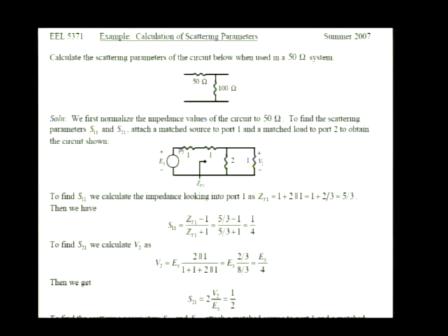Part of ES falls across these 2 resistors, and the remainder, V2, falls across the parallel combination of the 2 ohm and 1 ohm resistor. That's the part I want. How much voltage is there across that parallel combination? So, use the voltage divider rule. The voltage divider rule says the voltage in question is equal to the total voltage times the impedance of the portion of the circuit that we're trying to find the voltage drop across, divided by the total impedance.